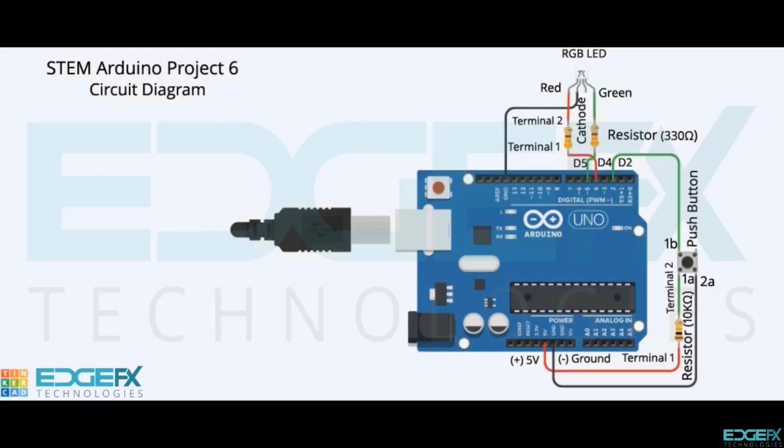To generate yellow flashing light. To summarize this step 6, we connect push-button switch, RGB LED and Arduino such that when the Arduino is powered and we press the push-button switch, the RGB LED goes on and off, or flashes in yellow color, for a specified duration of time and switches off when the switch is pressed again. This action repeats itself whenever the switch is pressed.